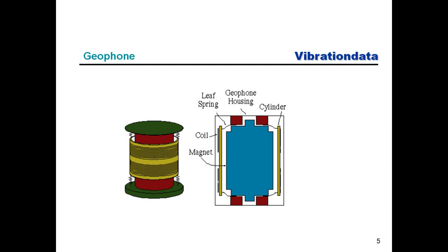And I think the idea there is that the magnet itself would be vibrating vertically, and the coil itself is mounted on very compliant springs, so that would tend to remain stationary. And then the relative motion between the coil and the magnet would cause a current or voltage that is proportional to velocity. So that's one way for directly measuring velocity.